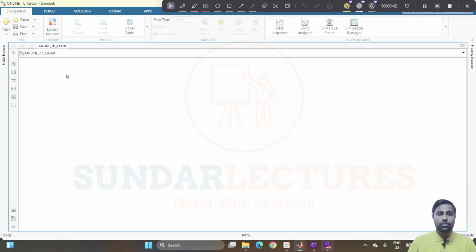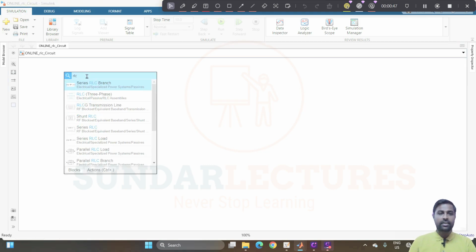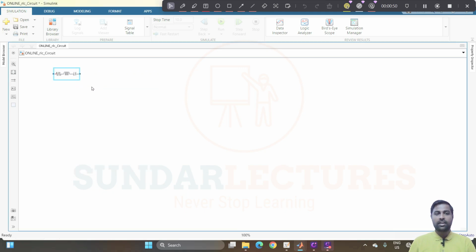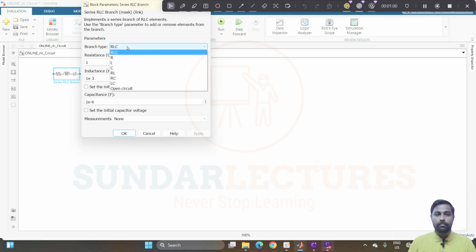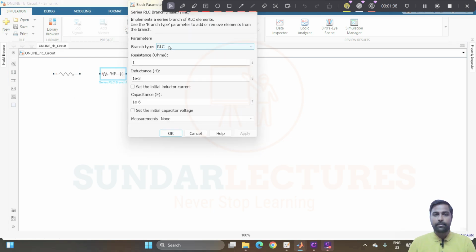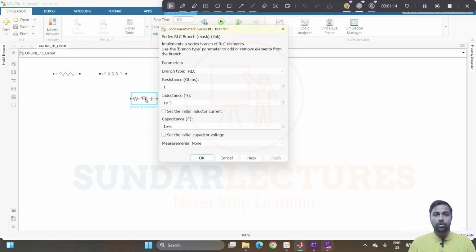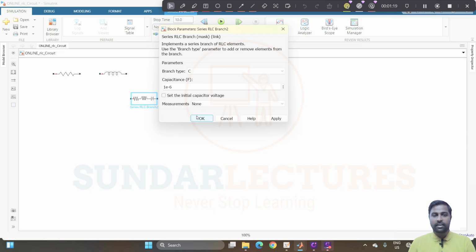Now double click here. You can see a create annotation block. Go there and you get the RLC series branch. Copy this and paste it, and paste it again. You can see three different RLC blocks. Go to the first one, go to the branch type, select R and click OK. Go to the second branch, and in branch type make it L and click OK. Go to the third branch, change the branch type to C and click OK, right?